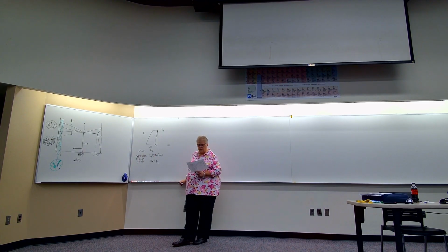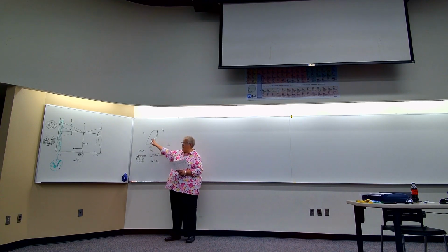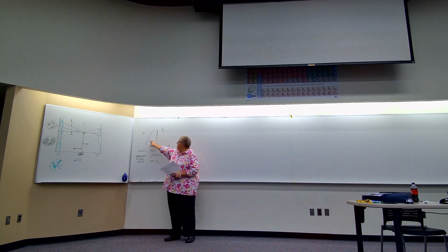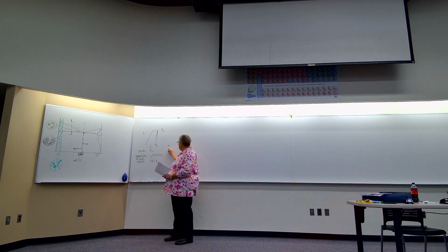It isn't labeled, so this is good. Between each single phase region and the next one is a two-phase region that has both of those phases. So in this area right here, just to the left of the eta 2 region, which has liquid on the left and eta 2 on the right, the phases are eta 2 and liquid, right?